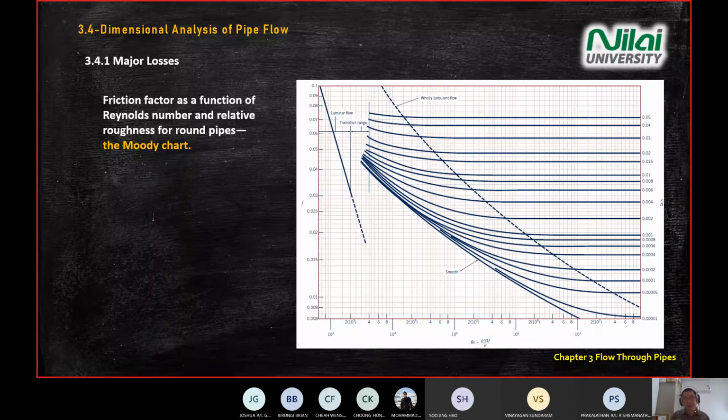It means if inside a pipe system, you know that the pipe system is in a fully filled condition, the diameter we are using is Di, which is the internal diameter of the pipe. So be careful on the D that you choose. All right, so this is just some highlight for the axes.